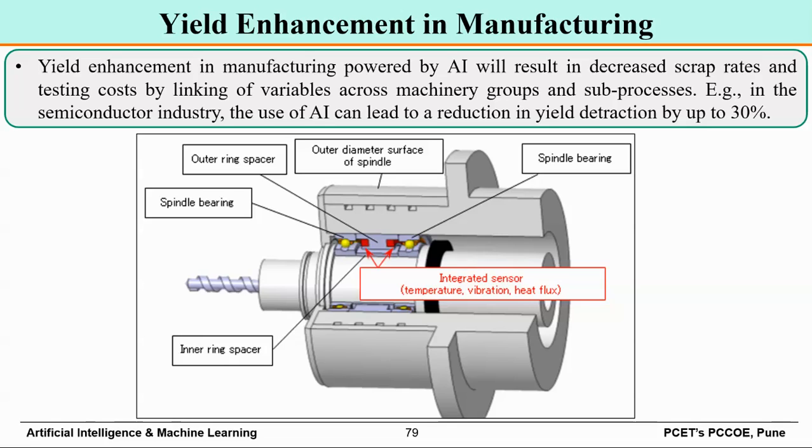Accuracy. So whatever component is manufactured, if the bearing is failed, then definitely there is an increased vibration level. So that mounted component is also vibrating. So during machining, whatever accuracy you are expecting from that component, you will not get it. So if the bearing fails, vibration will increase. If vibration increases, the component will tell you some symptoms. It will show that there is some problem in the bearing.